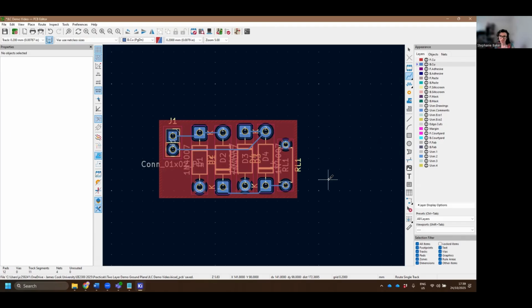Again, you would only do this if you didn't need to route on both sides. If you did need to route on both sides, the best option then is to turn both layers into a ground plane. That way you've got plenty of copper on the top, plenty of copper on the bottom as well to be the ground plane. And it's not as difficult to solder when we're getting it from JLC because you get the solder mask that stops you from shorting to your ground plane like you might have had happen during your milled board experiments.